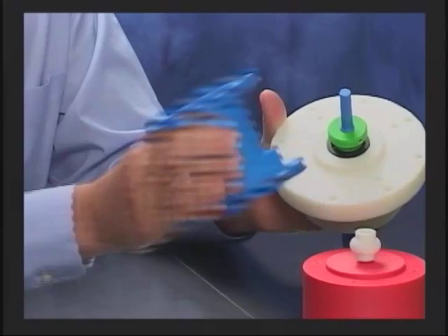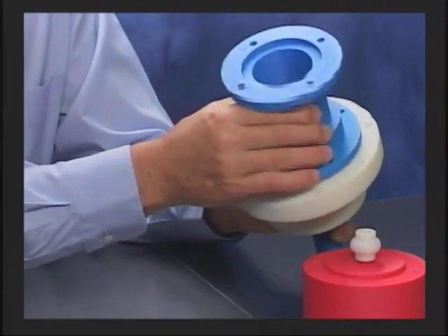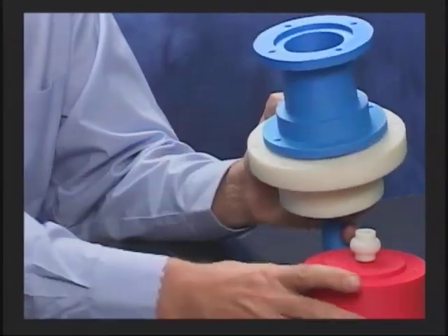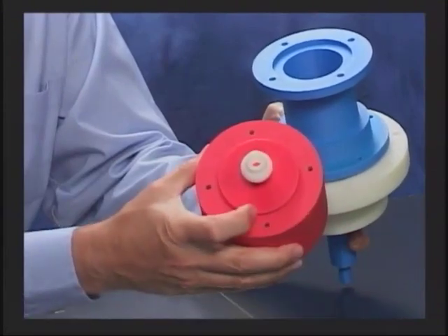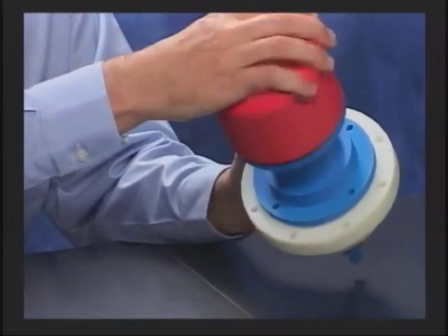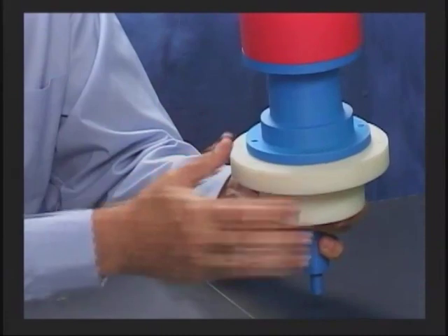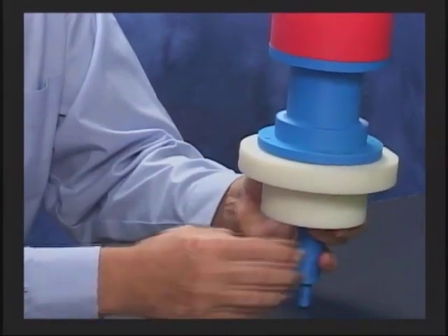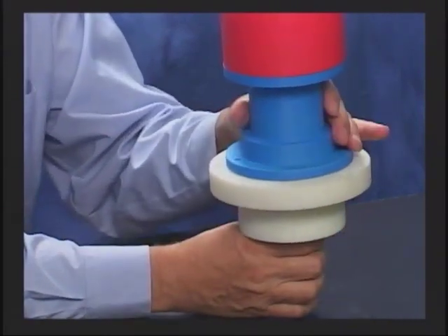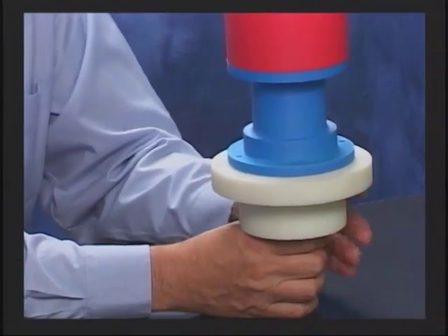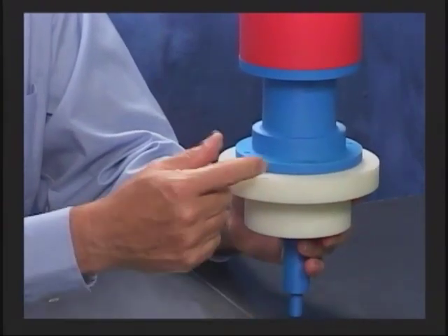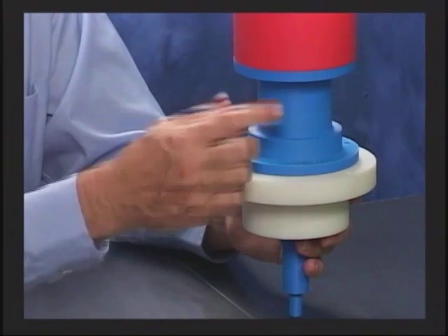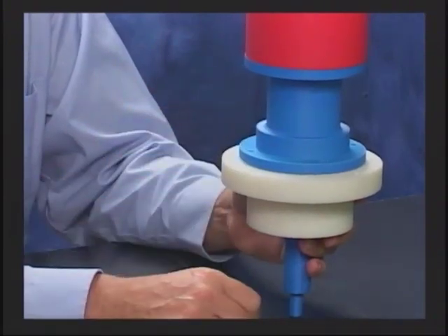When the two went on, that rattled around a little bit. Then when we took the motor and put it on, it had a diameter that fit inside a pilot, and that moved around a little bit. So we added all of those together, and that's how we came up with the total misalignment. It's pretty straightforward. Just add all of the joints up and it'll tell you what the final is.